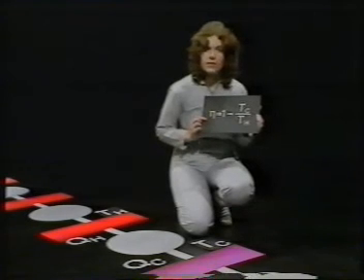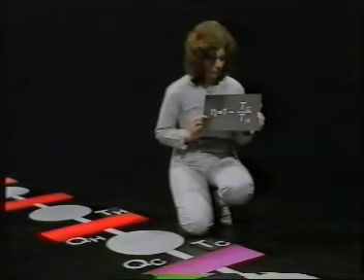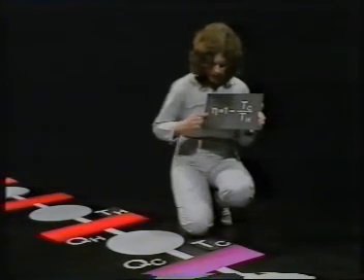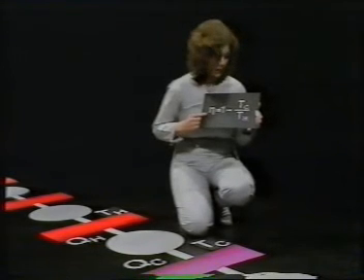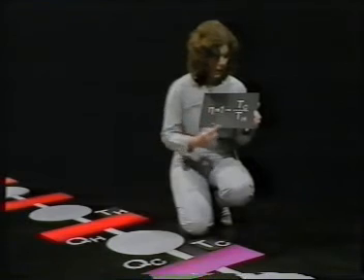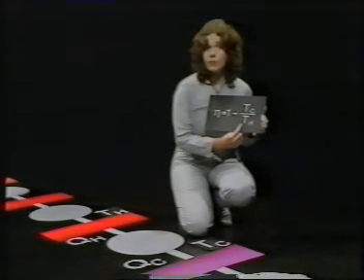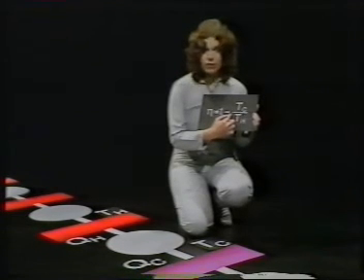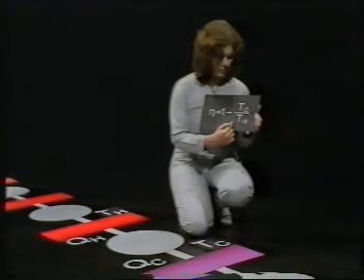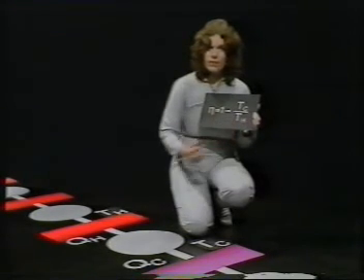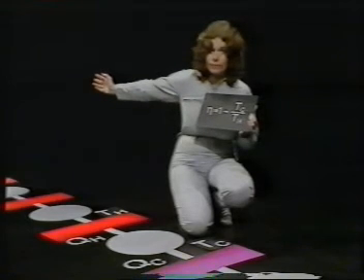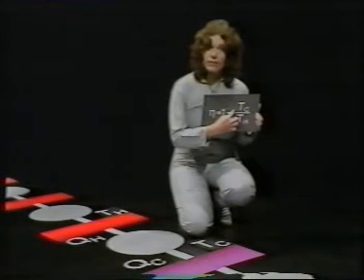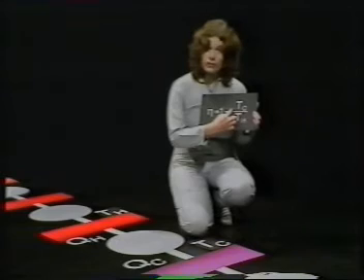I also know from the first law that the efficiency can't be greater than 1. And that tells me two more things about my temperature scale. If the efficiency is 1, then it's a limit, a maximum. And TC over TH must therefore be 0. That can happen in two ways. Either TC is 0 or TH is infinite. Now, if TH is infinite, then there is no limit to my temperature scale. If, on the other hand, TC is 0, then there is a lower limit, an absolute 0.